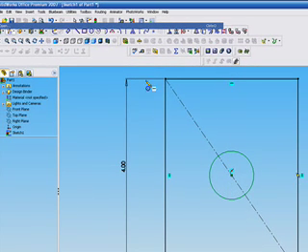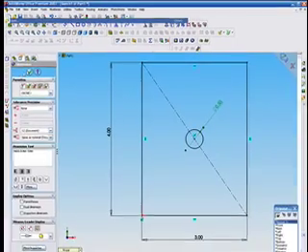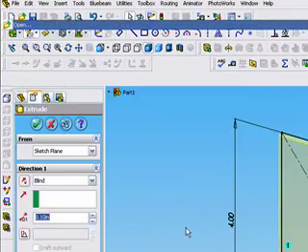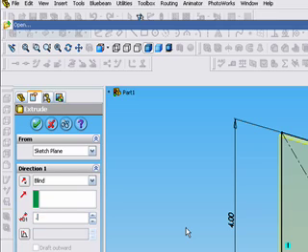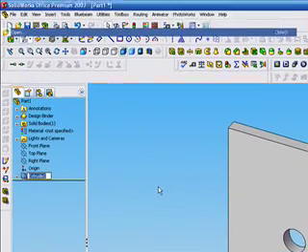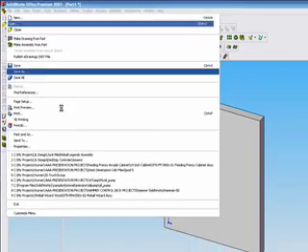For this particular thing, I'm going to make this a 1/2 inch diameter, and now we're going to give it its extrusion. We're going to pick 1/4 of an inch, actually type it in, click OK, and there's your first 3D part. Now when you start getting into this, you definitely want to save it, and we'll go ahead and save this.